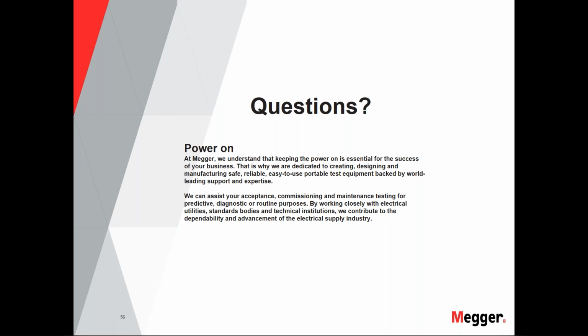It is not usual. We use third harmonic for 32 element because 32 element is applying fundamental frequency operation. Normally, we use the third harmonic for the ground elements like 95% element or 0 to 100% elements, not on the 32 protection. All right, excellent.